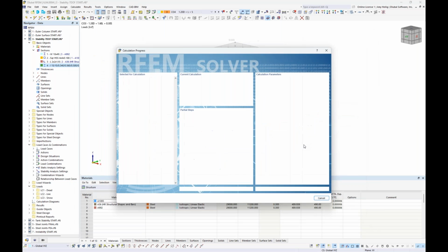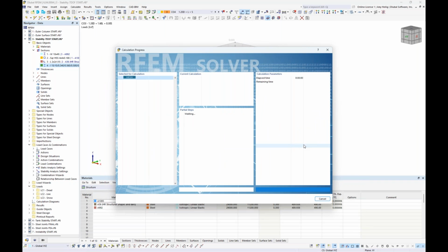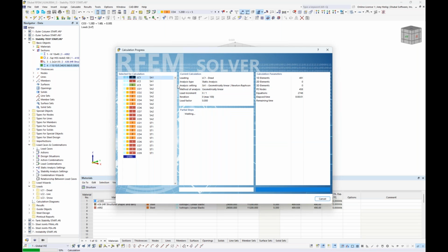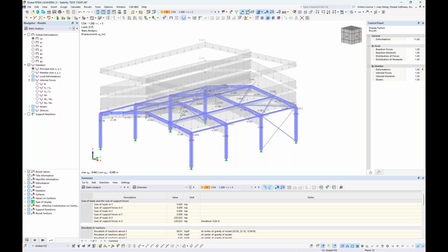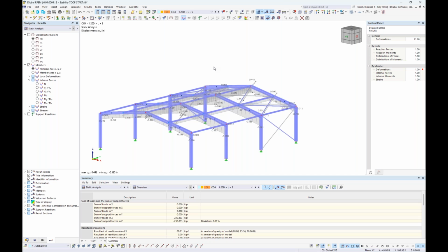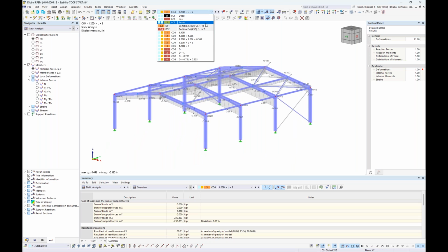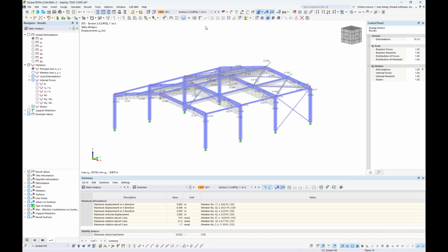So let us run through this calculation by running the Calculate All button. And as we will see, we will first run through the load cases according to first order, our load combinations using a second order analysis, but then we run through all of those load combinations again for the structure stability. So when we toggle this drop down to the design situation for our factored load combinations, again, this is nice because it's more or less an envelope solution for the static analysis.